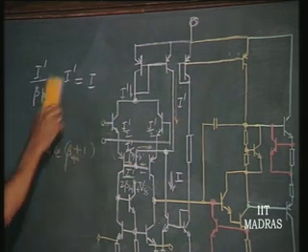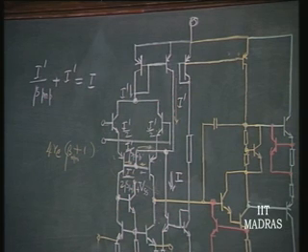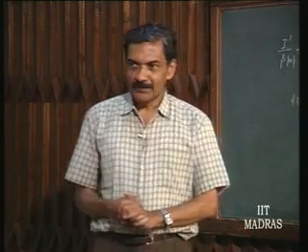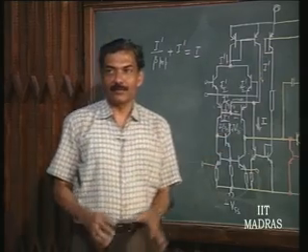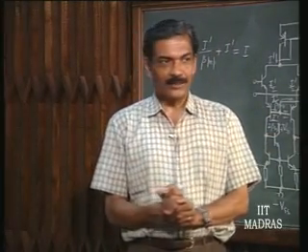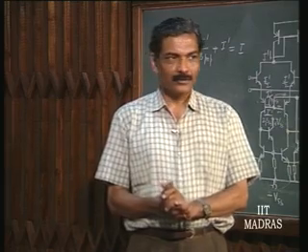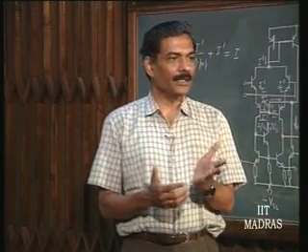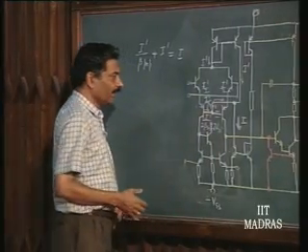So, you can see that the bias current of the input stage is fixed in a pretty complicated way compared to the conventional scheme of straightforward current mirror biasing. The mirror reflected current is made equal to the fed back current, which is equal to the emitter current of the operating transistors. So, for the given configuration, please find out, for the values of resistors etc., assuming supply voltage VSS and minus VSS as, let us say, 12 volts, the value of the operating current I dash. Beta P and P, you can assume to be something like 10. So, you will get the value of that.